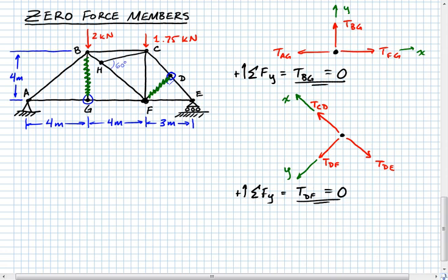If we think about here the joint at H, think about that joint right there and do a free body diagram of it. What we'll have is a force, let's say here, we'll do it in the correct orientation there. We have this force HF, and we have a force acting up here of BH. All right, and then we have this other force that kind of acts up like this.